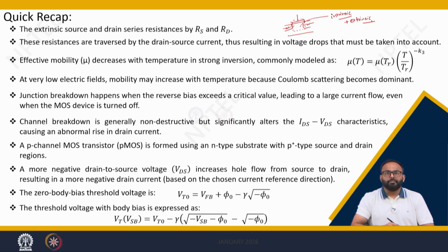In the previous lecture, we discussed a few of the extrinsic effects, which we can call parasitic effects: source and drain resistances, temperature effect and breakdown.